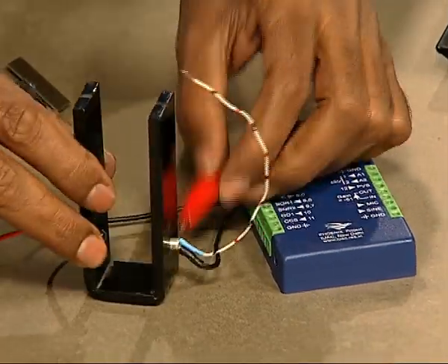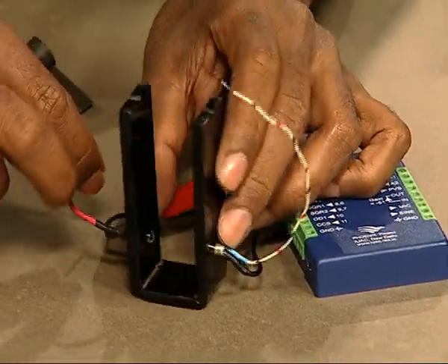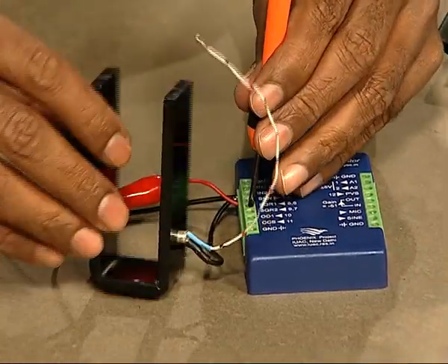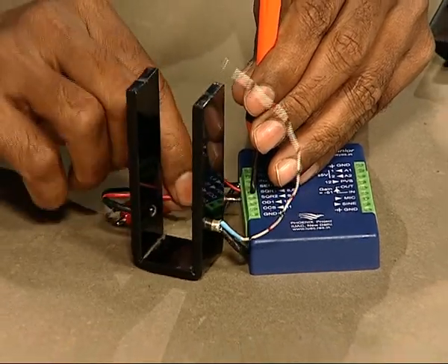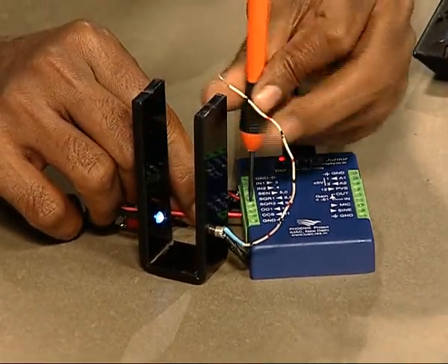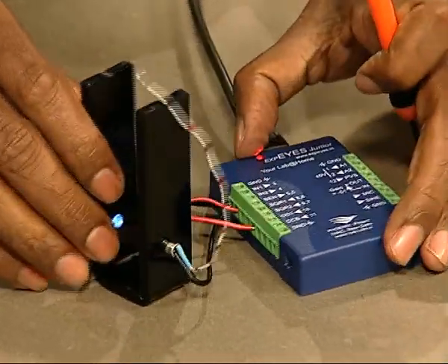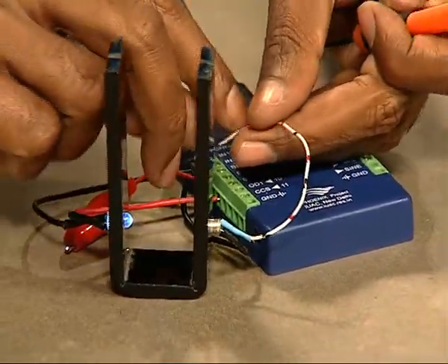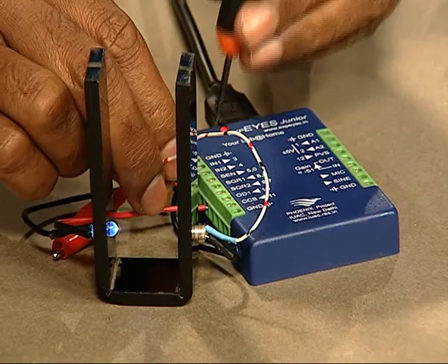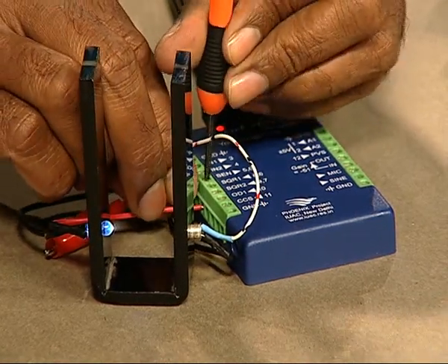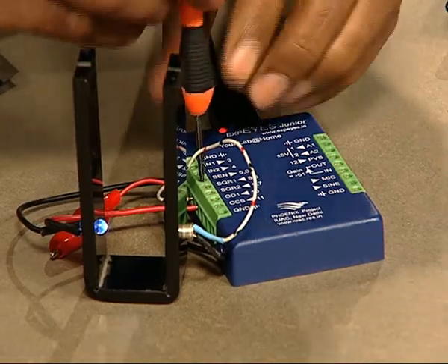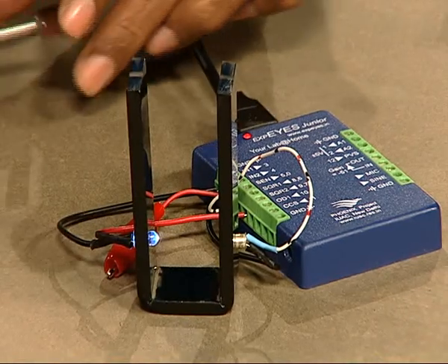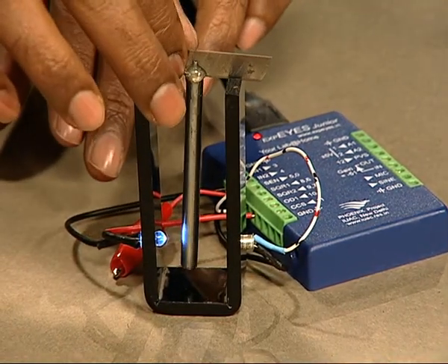Now we should have some way of powering the LED. We can connect it to our SQR1 output, which will power the LED. So, we just connect that to the SQR1 output, and now the only thing left is the collector of the phototransistor, and that is connected to the sensor input. As you know, this sensor input can measure resistance. So, now we have made the connections and keep the pendulum here,